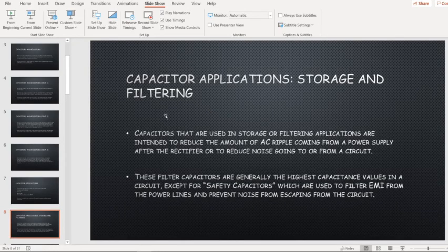But what that does, like in a DC power supply, is draw the AC down to ground, because capacitors do not allow DC to flow. It allows AC to flow, though, so it's able to filter that. Now, that being said, the first thing that I will mention is a parasitic property of capacitors, which is known as leakage current.